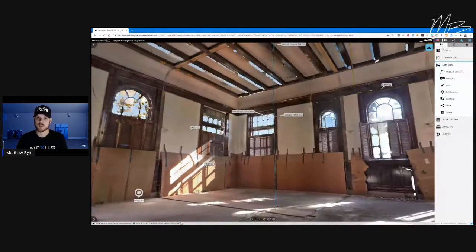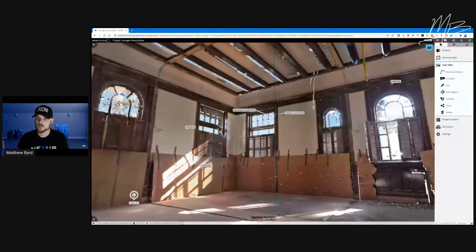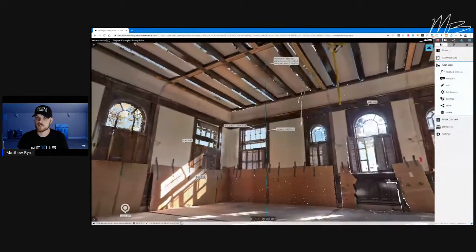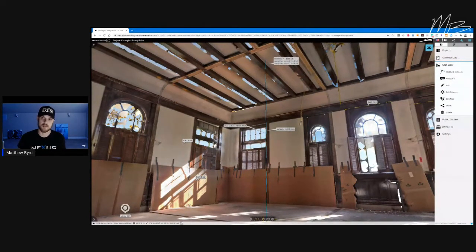So instead of utilizing the overall measurement it pulled, with the difference in the X and the Y, it'll tell me just the vertical difference between those 2 points. That's kind of useful when you're looking at clearances and such, whether it be power lines or doors, or you're looking at fitting equipment in.